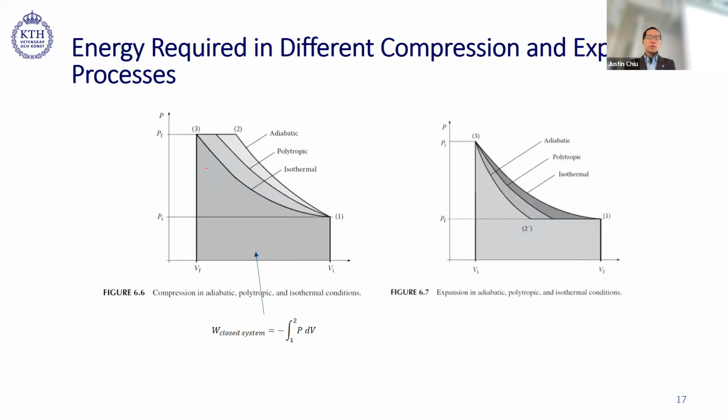And then if we want some more illustration, a picture that's more representative, let's place it in this PV diagram. So the y-axis is pressure, the x-axis is volume. We know from definition, closed system, it's minus PdV, and we know the open system is the integration of VdP, right?